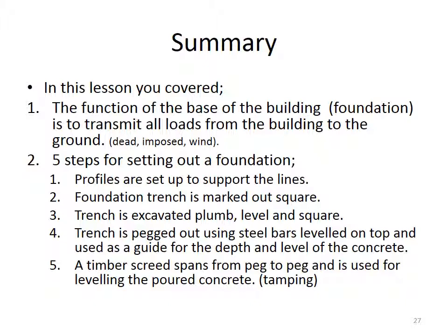Number 4, the trench is pegged out using steel bars levelled on top, and these are used as a guide for the depth and the level of the finished concrete foundation. Number 5, a timber screed spans from peg to peg and is used for levelling the poured concrete by tamping it up and down and also sliding it back and forth, making sure that the concrete finishes level with the top of the pegs.